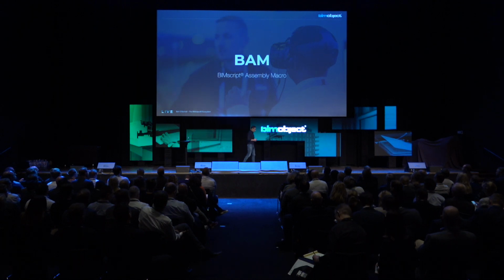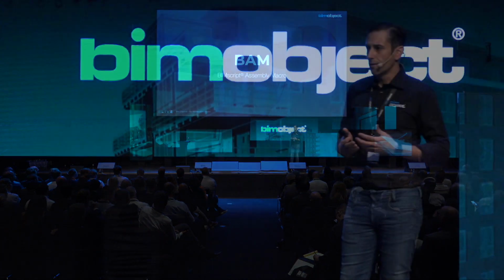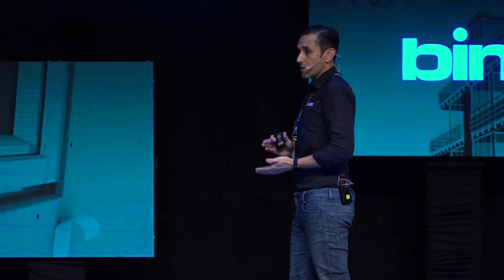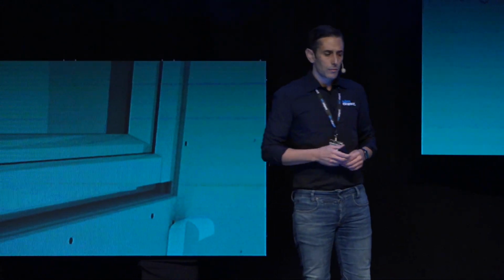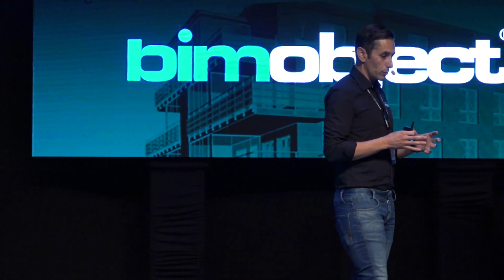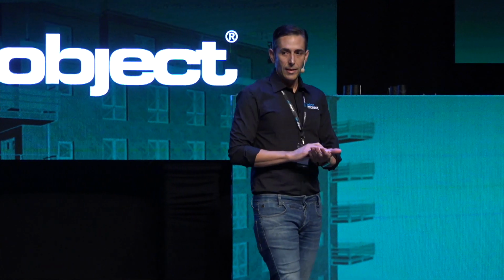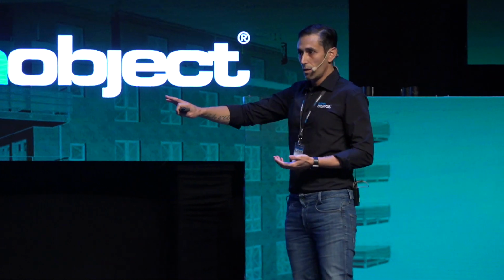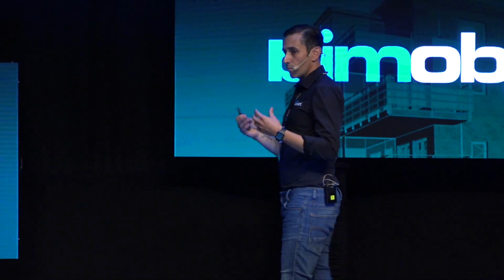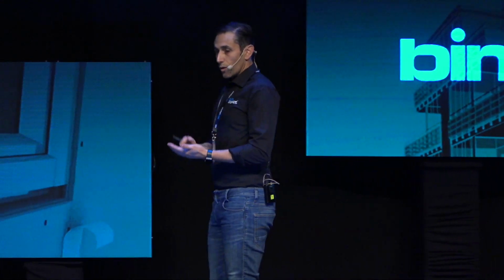In a construction process, if we look at a design process, as Stefan mentioned, there's a lot of studies out there that tell us that those models get flattened around 7 times. So there's a false sense of security that if someone builds an informational rich BIM model, they're going to mitigate risk by flattening it out and sending a 2D drawing to someone else. When in fact, they're actually increasing risk. They're increasing risk by making a lot of guesswork. So the next consultant will do the same thing. They'll build up a nice model so they can do all of their calculations. They'll flatten it out and send it to the next one.